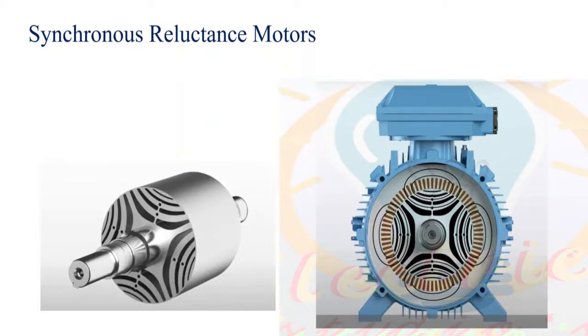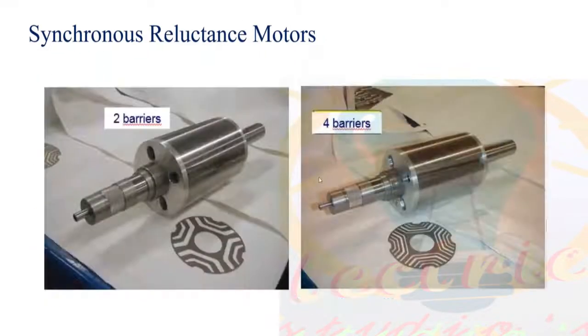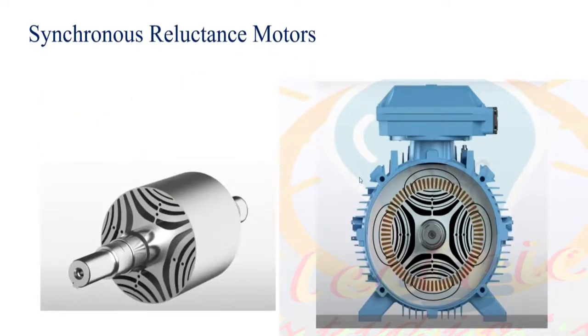And what did Tesla do? They used permanent magnets inside the rotor. I'll come to this slide later. On the rotor side, they embedded the permanent magnet, and Tesla calls it a permanent magnet assisted synchronous reluctance motor. So the problem was solved. People were telling that the synchronous reluctance motor can never be used in an electric vehicle, and these guys have proved that it can be used. In the Tesla Model S, especially in 2-3 models, the front wheel is driven by this synchronous reluctance motor, and the rear wheel is driven by an induction motor.